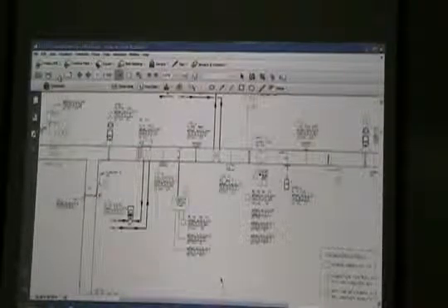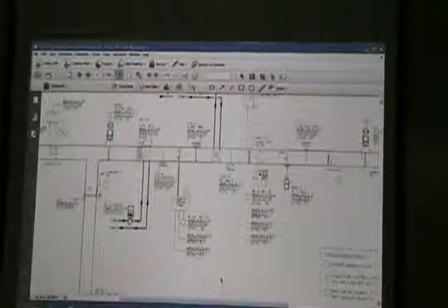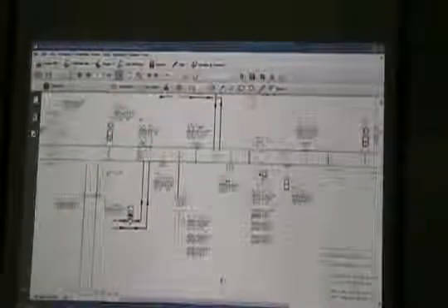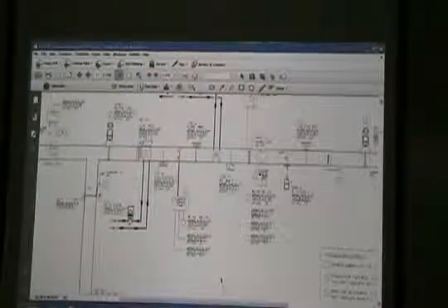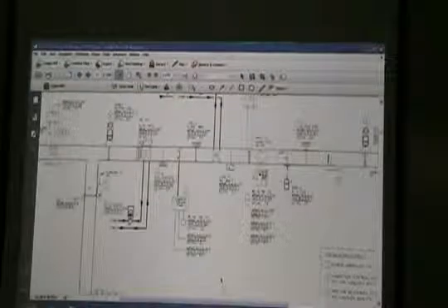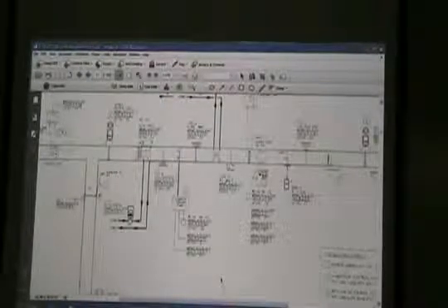Preheat coil with integral face and bypass. There's the preheat coil. We've got a heating valve. It's hot water. And those represent dampers. There's a damper actuator right there. We've got a point to control the damper actuator. We've got a point to control the valve. We've got temperature right here.